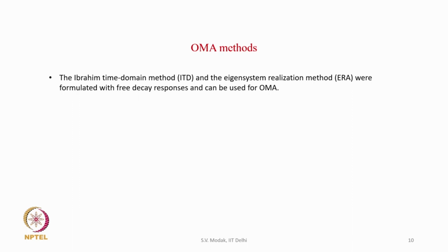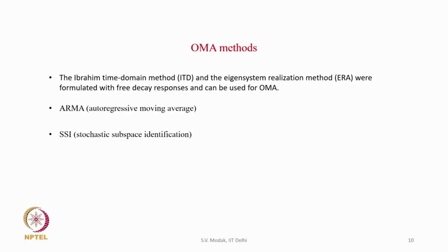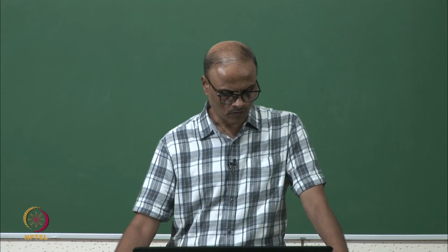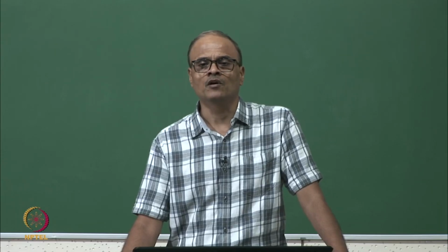So, that is why some of the time domain methods like ITD and ERA can be used for operational modal analysis. There are some other time domain methods, like the autoregressive moving average method and the stochastic subspace identification method, that have also been specifically developed for operational modal analysis. Some methods have also been developed in the frequency domain. One of them is the classical frequency domain approach, which is basically like the peak picking method. There is also an approach called frequency domain decomposition and enhanced frequency domain decomposition. These latter approaches are based on singular value decomposition.